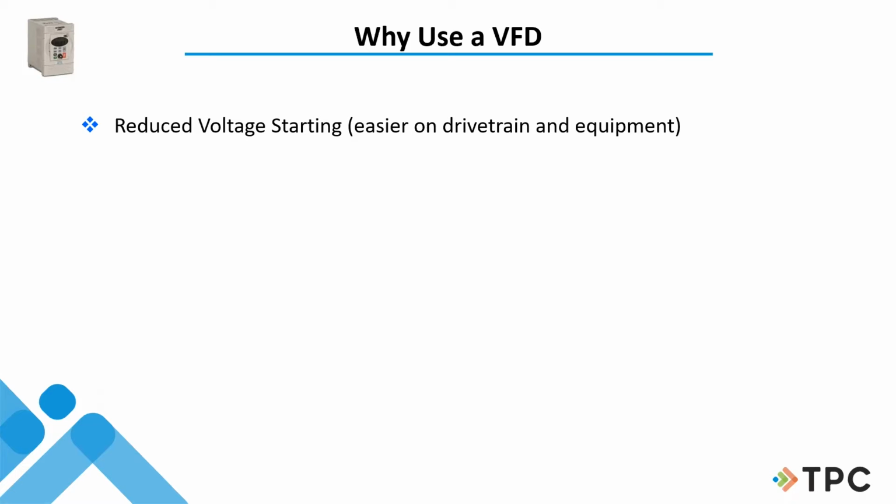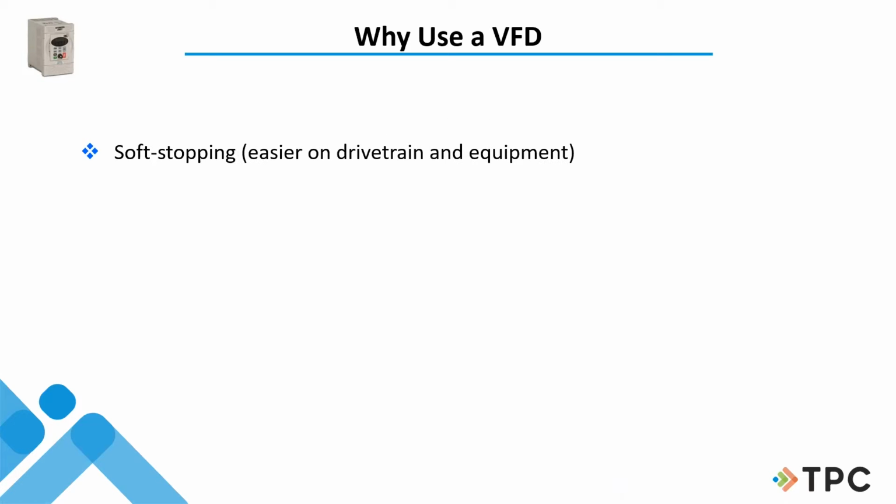Therefore, I would tell you that a VFD can be probably one of the best maintenance tools you can buy. It's a great preventive maintenance tool in that it really reduces a lot of wear and tear on the drivetrain. It reduces wear and tear on the couplings and all those kinds of things. When we go across the line, boy, we get that full power right away and things jerk. Well, we don't have to do that with a VFD. By introducing the right parameters into the drive, we can really reduce that. We can start things up and have it go much easier.